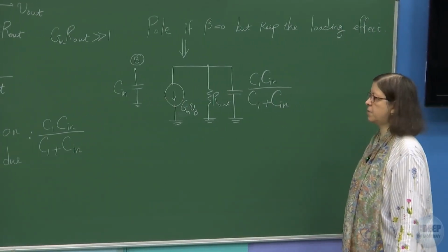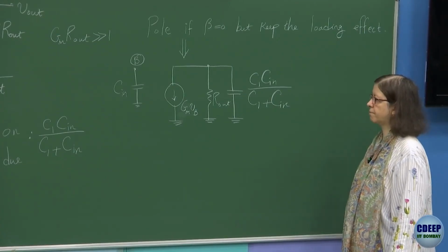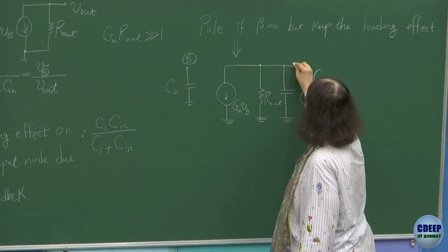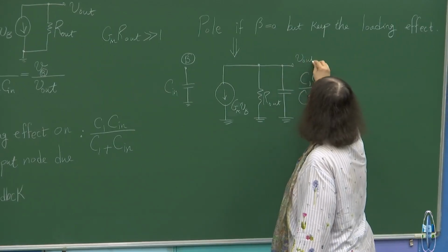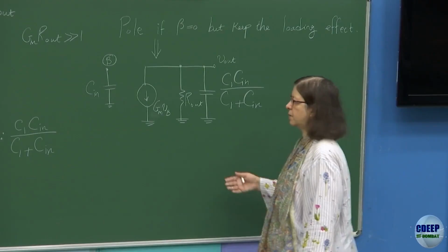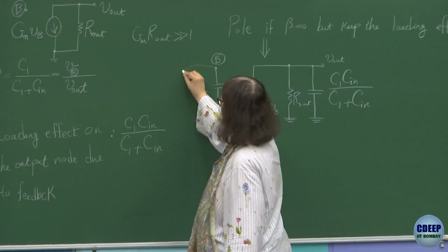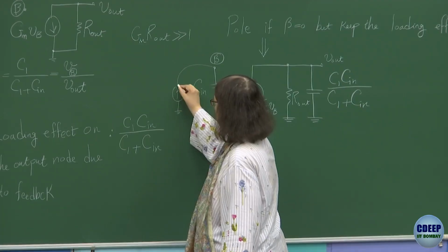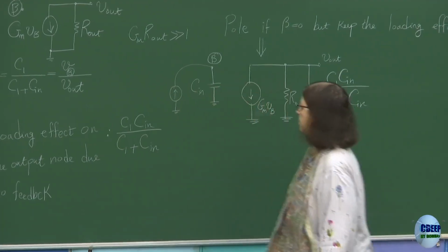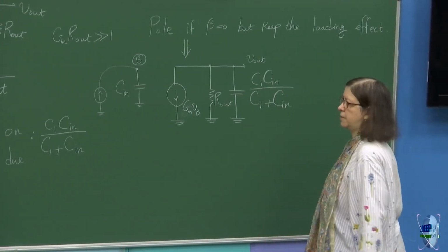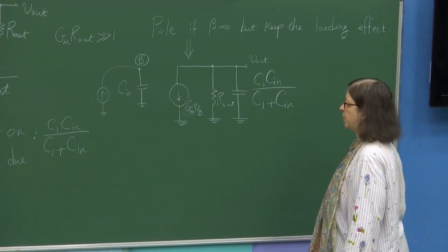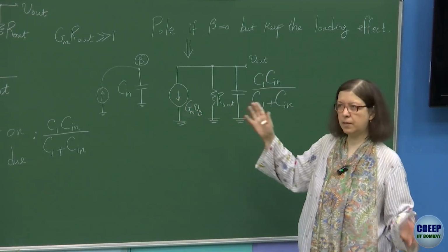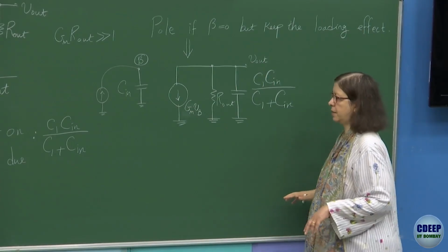Fine. This is the model, and this is Vout. We have one pole at s equal to 0. I told you, if you want to excite, you need to excite with a current source so that the model will not change. So Cin eventually creates a pole at s equal to 0, which is not actually the concern right now.